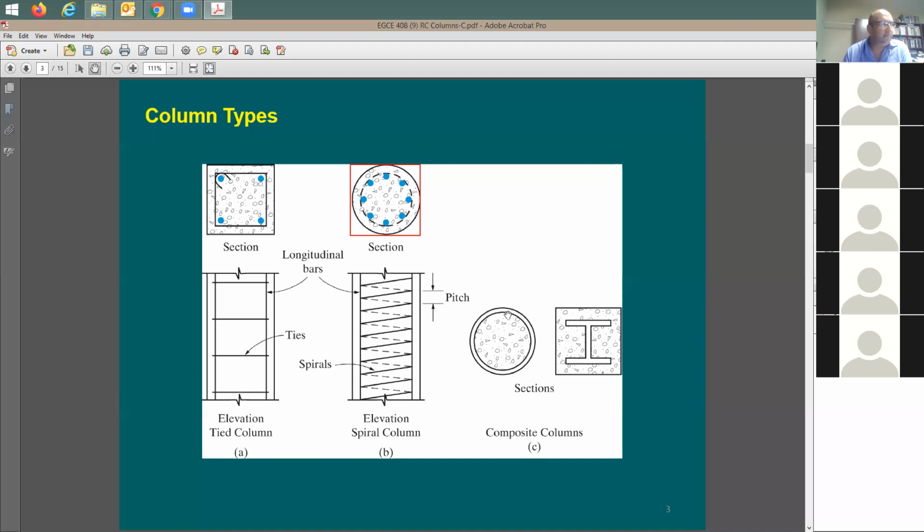Now I'm thinking here, what is the need for the vertical rebars? These vertical rebars also support vertical load. So if the vertical load is coming down, this concrete section supports this vertical load, and also these 4 rebars support the vertical load. So the rebars and the concrete, now which rebars? I'm not talking about the ties. These vertical rebars, these 4 rebars, and the concrete, both of them as one element, one structural member that we call the column, support the vertical loads.